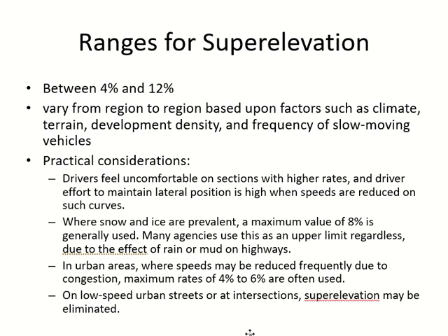Development density. Development around the road. If the development is higher, more population, so traffic will be high or low? High. What about the speed? Low. For lower speed, do I need more superelevation or less superelevation?